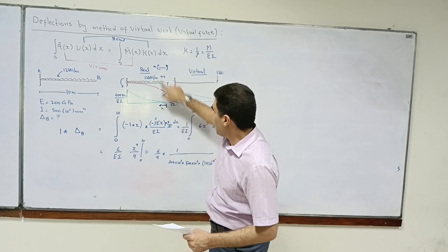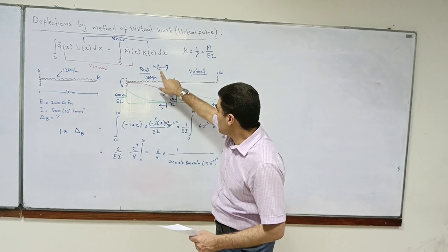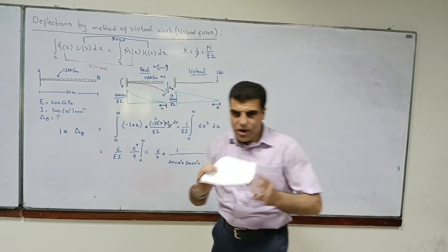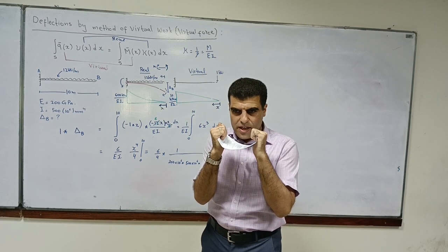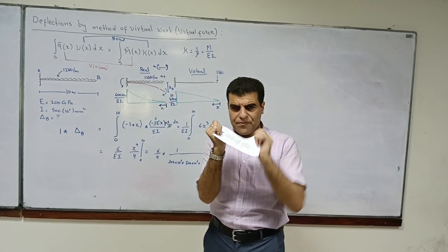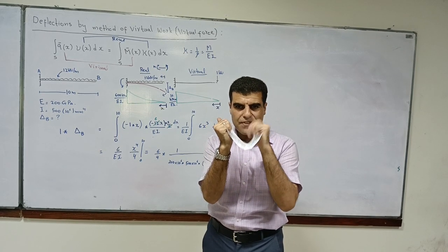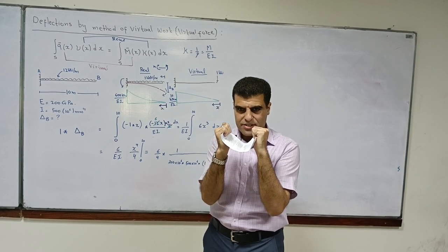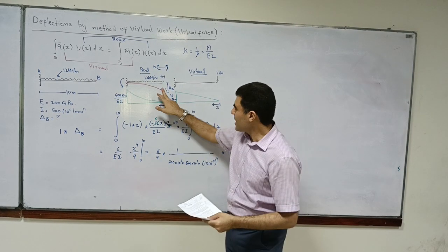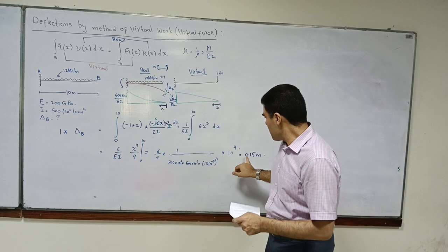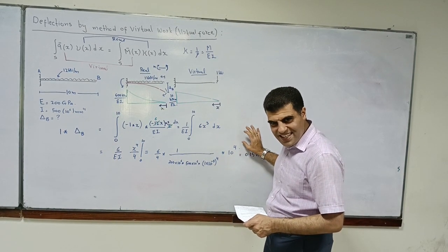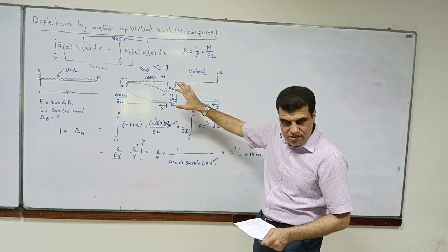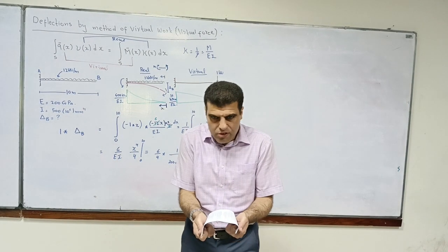Look, the moment profile and deflection, they must be agreeing with one another. That's what my point is. The moment distribution and the deflection must agree with one another. So, this is our positive moment. In other words, hogging is our positive. So if you have a beam which hogs like this, the deflection is positive. Why? Because the deflection and the moment are in the same direction. Agreed? If your deflection is positive, that means it is consistent with whatever you have with your moment direction.